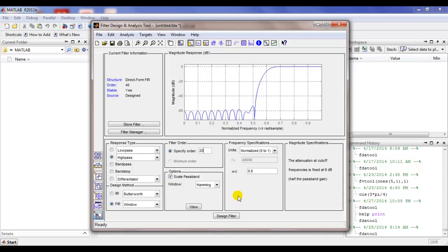So I'm going to get now this peak amplitude down to -74 dBs. It will go down even further. This passband will look even more straight. But what is the effect that is going to have? The transition is now going to become 3 times. So now you will go from stop band to pass band, it will take you 3 times as much as the rectangular window.